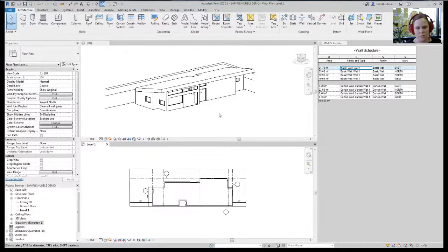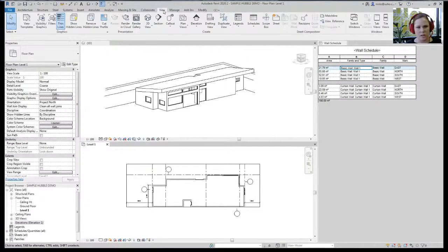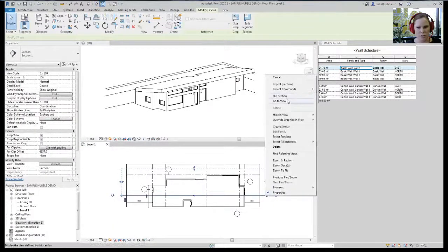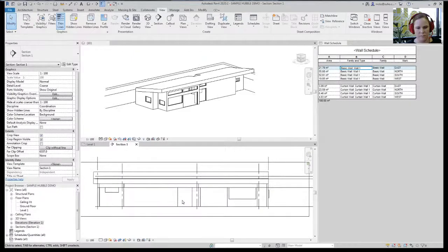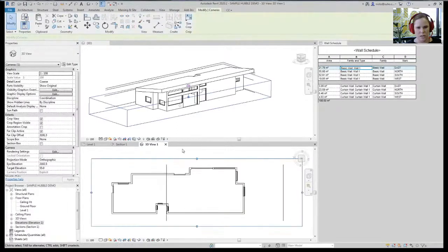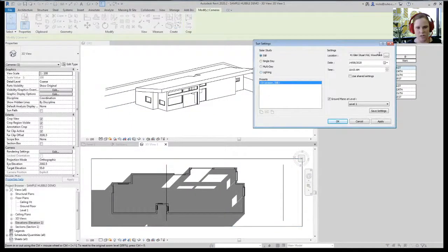I'm just also going to show you a little trick in terms of performance, just on a sidetrack, very quickly. So I've had a lot of questions about how to look at the daylighting inside one of these models, because normally as designers, when we cut through in a plan and then try to turn on the shadows, it won't show everything the way that you want it to. It'll show the shadows coming in at 1100 high off the ground floor plate. And in this instance we actually want to use a 3D view but turn off the perspective. And then if you turn on your shadows, you should actually be able to get the proper penetration of that daylighting.